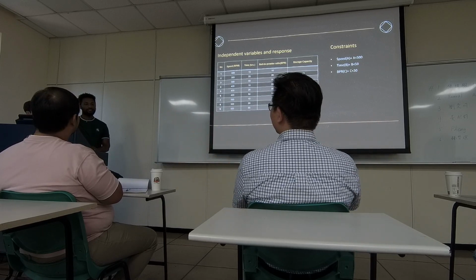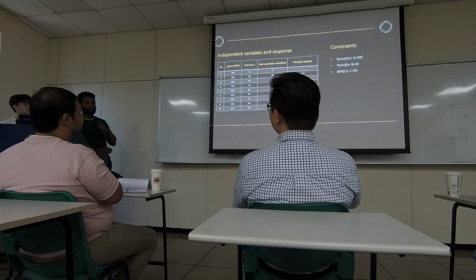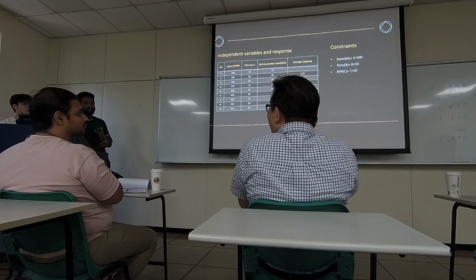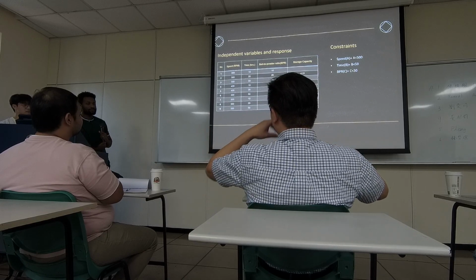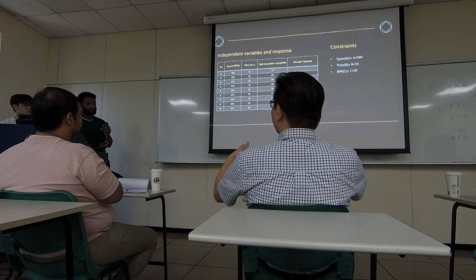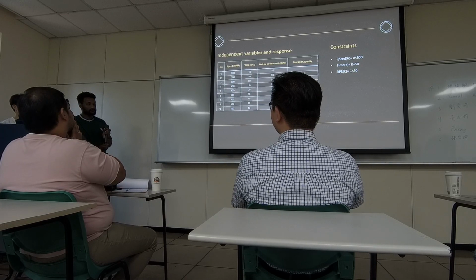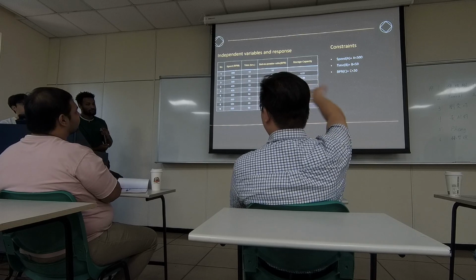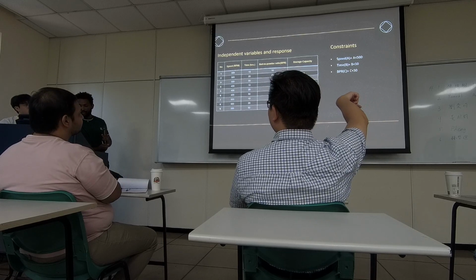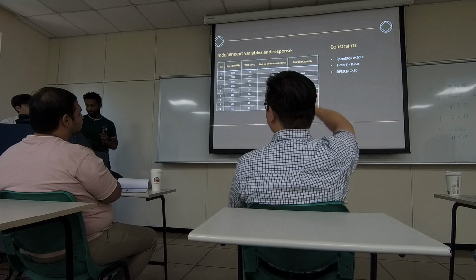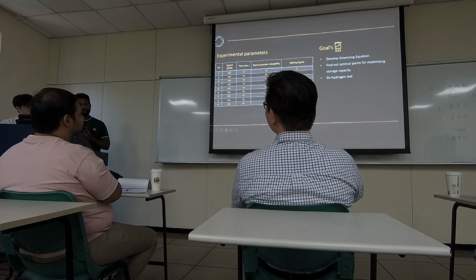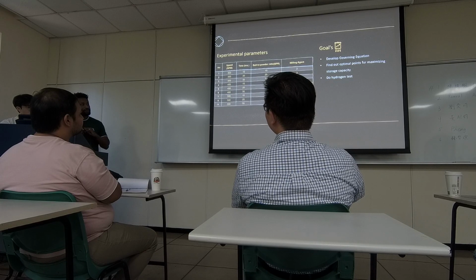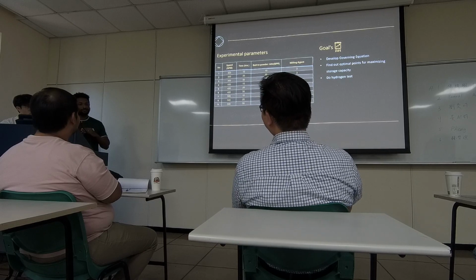Your question is the objective function will not predict well? Because there's nothing to prove. Usually if you build a response surface, you want to show how accurate your model is. You need enough data to show. Let's say you take one out and use 3 of them as your training, and then use 1 for testing. At the end, you may get a pretty poor result. Trust me. Just trust me on this, okay?